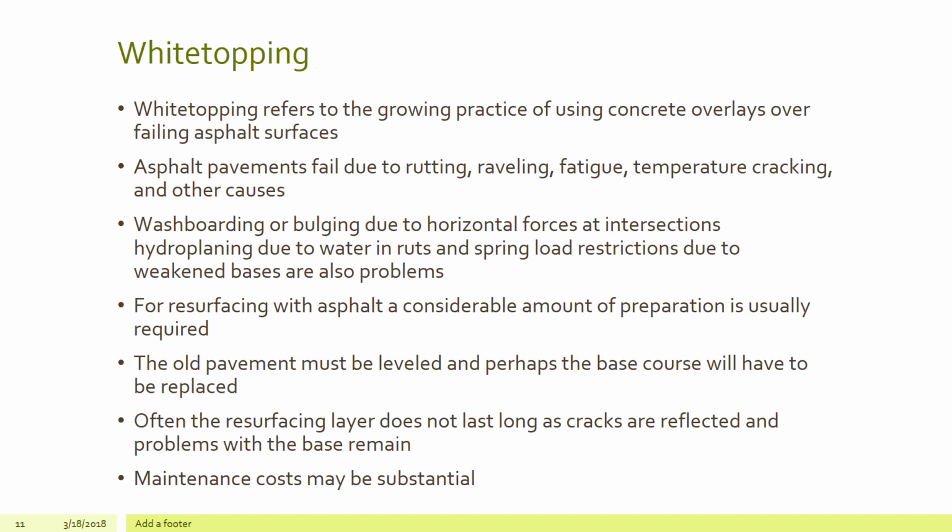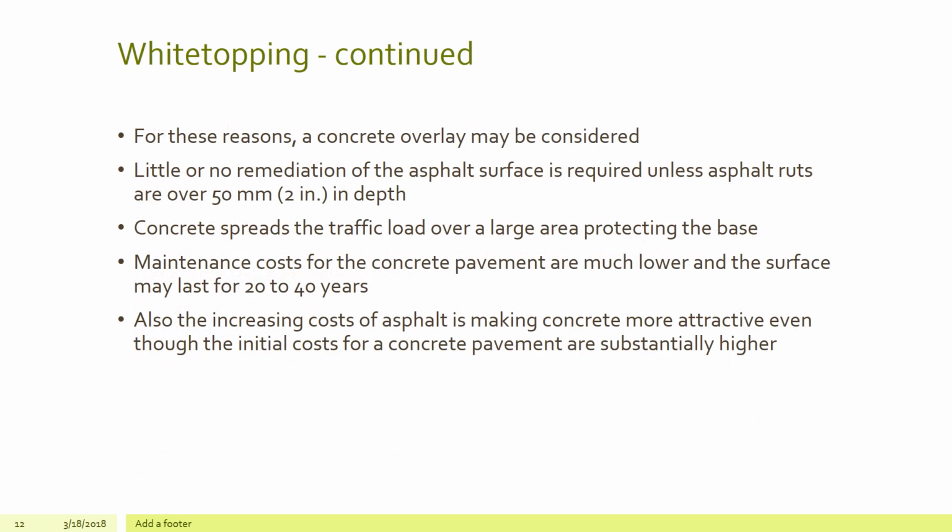For resurfacing with asphalt, a considerable amount of preparation is usually required. The old pavement must be leveled, and perhaps the base course will have to be replaced. Often, the resurfacing layer does not last long as cracks are reflected and problems with the base remain. Maintenance costs may be substantial. For these reasons, concrete overlays may be considered.